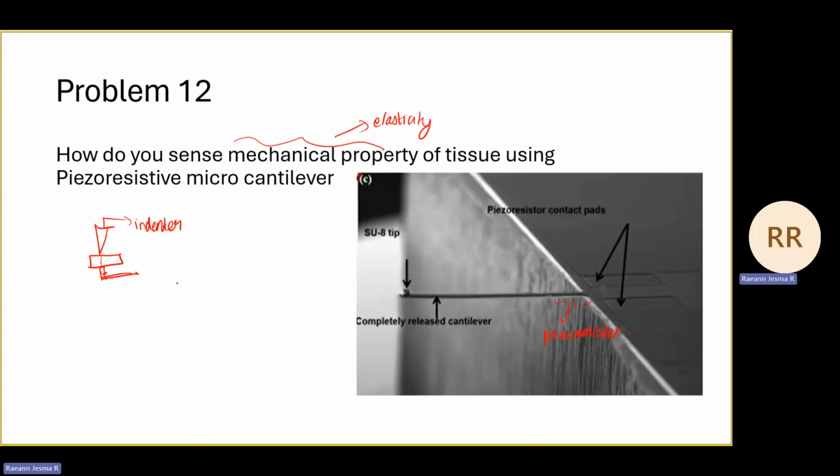Depending on the amount of bending of the cantilever, we'll have some strain generated at the fixed end. Why are we having strain generated? Let's say the cantilever is bending like this, and here our structure is fixed. In this region you can see it will start to get compressed, and at the top it will start to get stretched out. The material gets stretched out at the top and compressed at the bottom. So there is some amount of stress present at the regions where it is constricted.